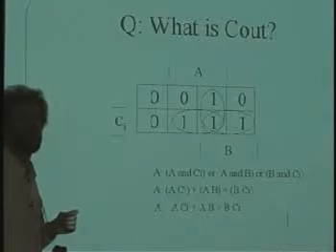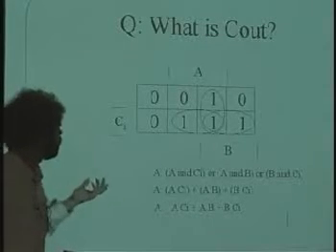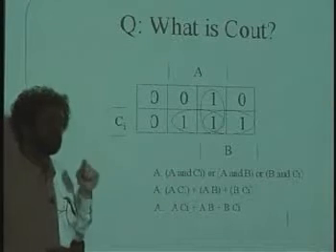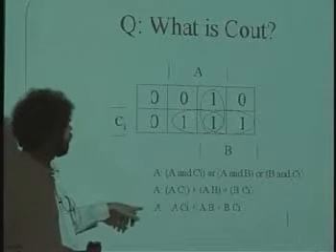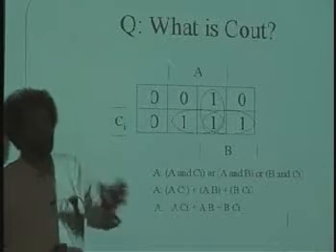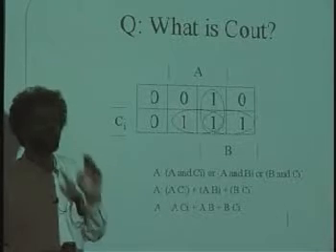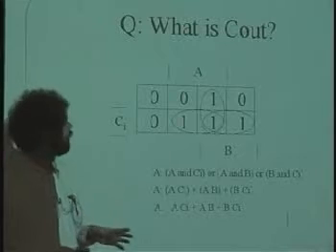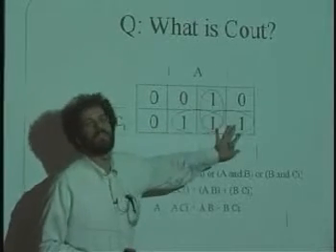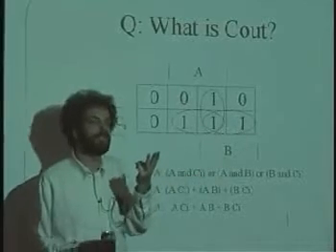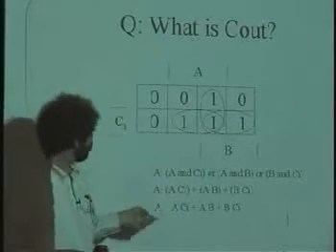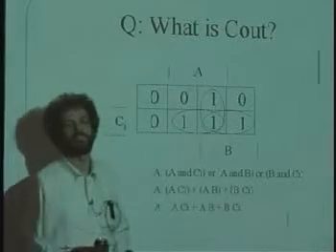Now you could do it, but it would take a lot to finally see the symmetry and all of this stuff. And if you think about it a little bit more, what is the logic here actually saying? That at least two of these have to be 1. You got it. That two or more of the inputs need to be 1. And this tests for these two inputs, this tests for the other two inputs, and this tests for the other two inputs. You have 3 wires. There's 3 ways to test for 2 of them being 1. And so you just OR up those 3 cases.